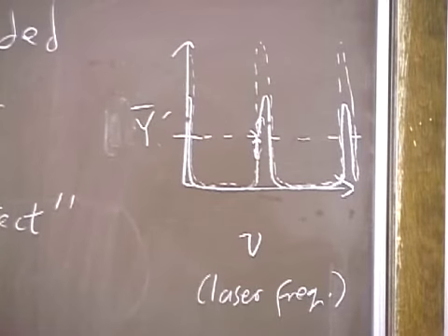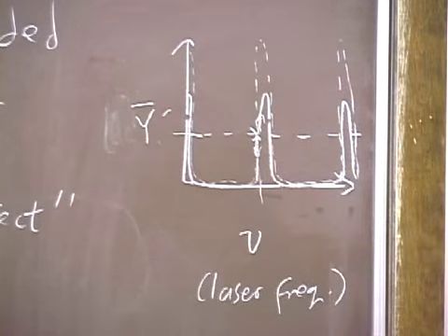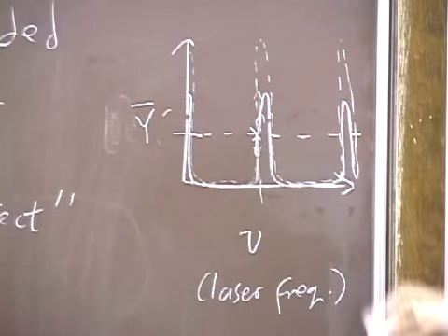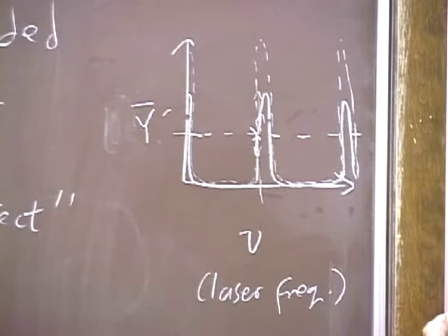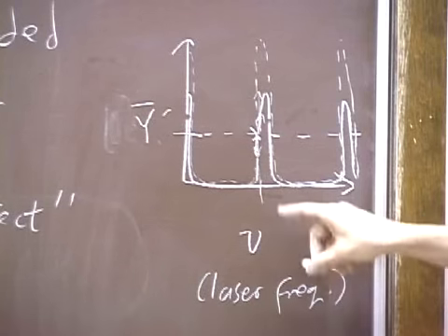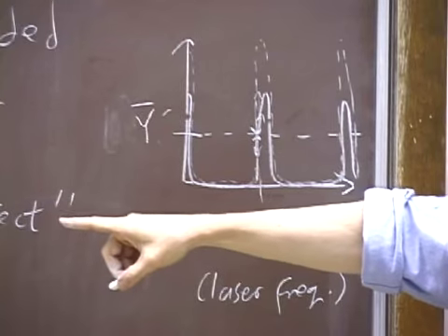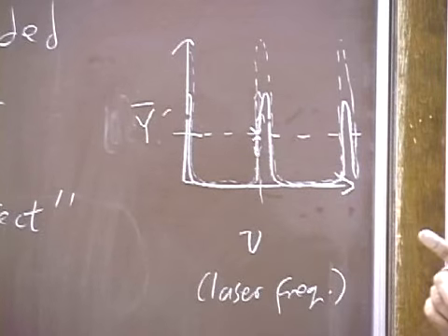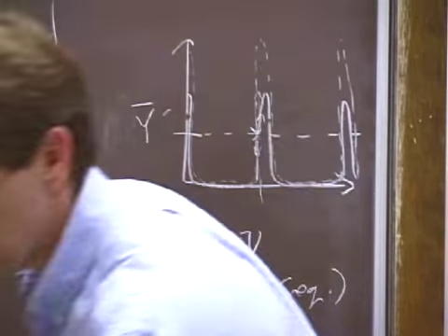then the transmitted beam, the intensity of the transmitted beam can increase. And even if the laser frequency hasn't changed, then the intensity that the photodiode sees can jump way up. Then the servo, not knowing the difference between an intensity fluctuation and a frequency fluctuation, corrects it by changing the frequency. And all it does is hold the power falling on that photodiode constant. And so what we've done here is we've actually introduced frequency noise into the system by coupling this intensity noise back into the frequency. And that's a problem.